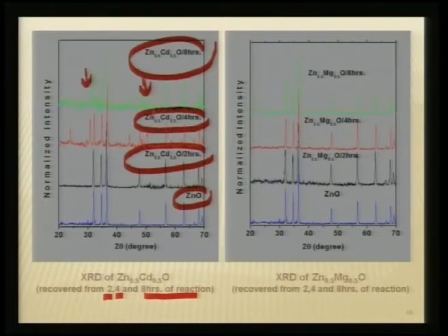What does that mean? This seems to be a kinetic growth, and with more and more nucleation, your cadmium is not actually getting doped into zinc oxide, whereas the cadmium hydroxide first starts nucleating and then it starts building up into a crystalline matrix. Therefore, along with zinc oxide, what is actually growing is the cadmium hydroxide particles, which are coming out as nucleated features. So more and more cadmium hydroxide gets nucleated, then it crystallizes as a crystalline phase.